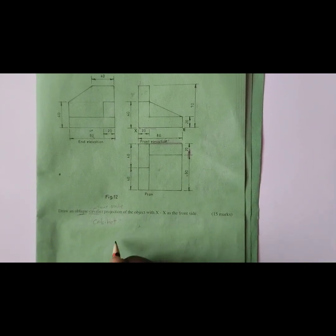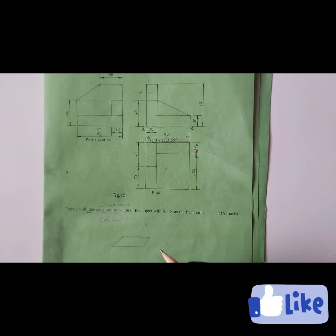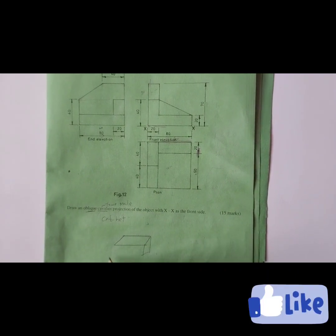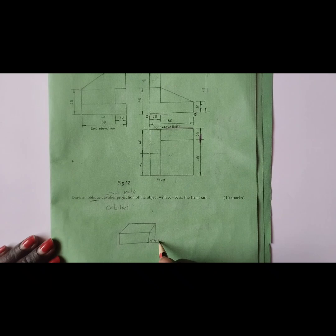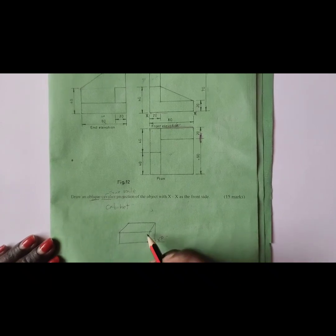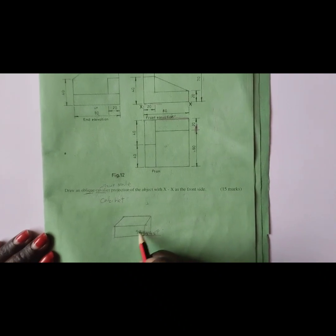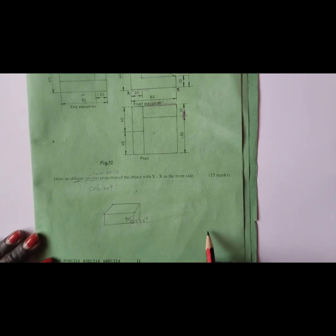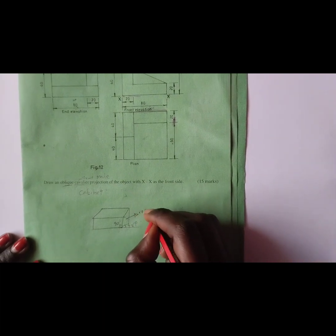you need to know that you must have the dimensions of the oblique box. Now this is our box. Remember, in our oblique, one side is inclined at an angle of 45 degrees, and on this side it is perpendicular to the height. This one forms 90 degrees, or you can say it is 180 degrees. It is a straight line. So remember, this 45 degree side is the receding side.